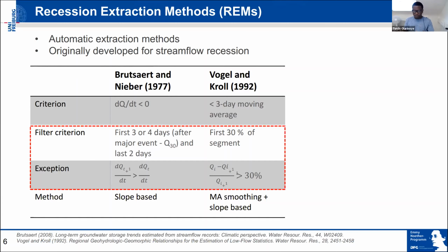So these restrictions, filters, and exceptions are imposed there to remove superfluous flow or quick flow or first runoff contribution, which in Karst hydrology would actually mean that we are removing the quick flow component of the Karst spring recession.